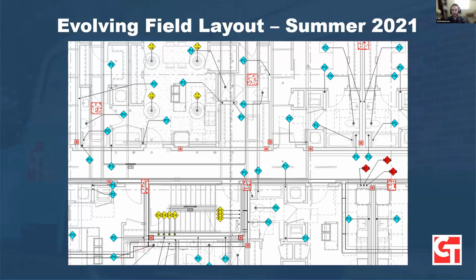From there, we would generate a point file. As you can see, some of these points centered on sleeves and embeds. And then we sent that to our concrete contractor, who actually handled the layout process for us as part of their formwork layout. It was a pretty effective process. There were a few lessons learned along the way, and I'll get more into detail on the actual workflow of doing that point layout later on in the presentation.